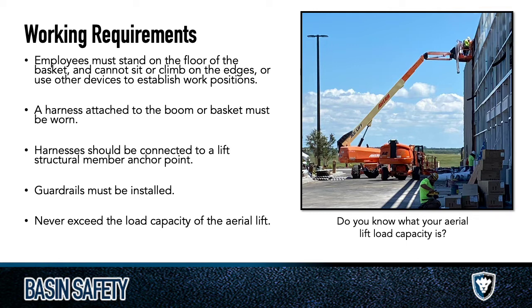You want to make sure that you're tied in. Sometimes they can be a little goofy, like the anchor point, so make sure you're attaching to the anchor point and not to the handrail or the guardrail. That is not the anchor point. You want to make sure that it's a good harness. It allows you the ability to move. You're not sucked up too tight to where you can't work. Obviously, that will kind of incentivize you to disconnect from your anchorage.